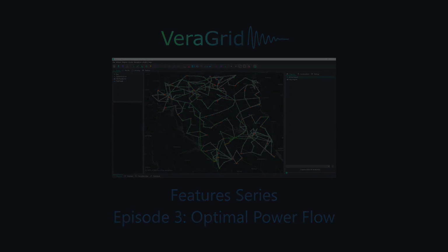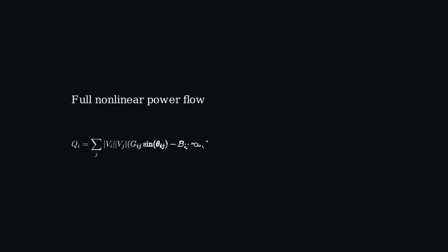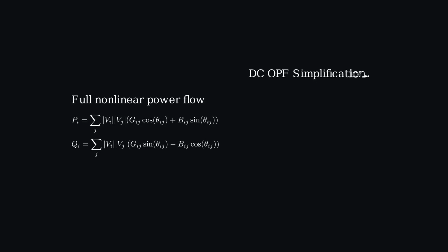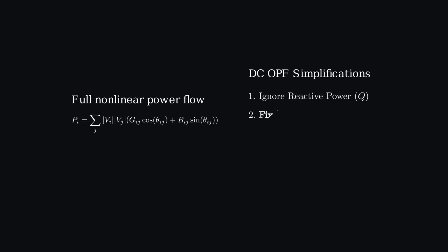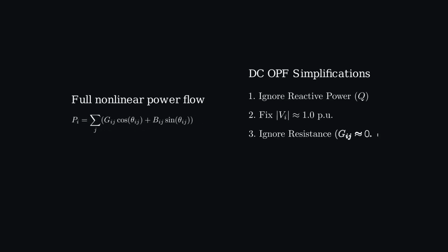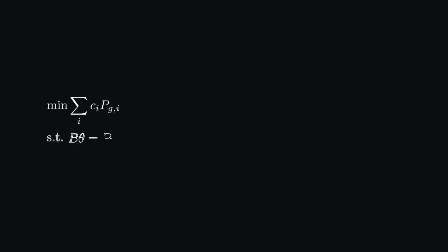and within technical limits? The DC optimal power flow remains the standard formulation in most cases. Very similar to the conventional power flow, it simplifies the network equations by fixing voltage magnitudes to 1 per unit and focusing only on active power and phase angles. This turns the problem into a linear optimization that can be solved efficiently even for very large systems.